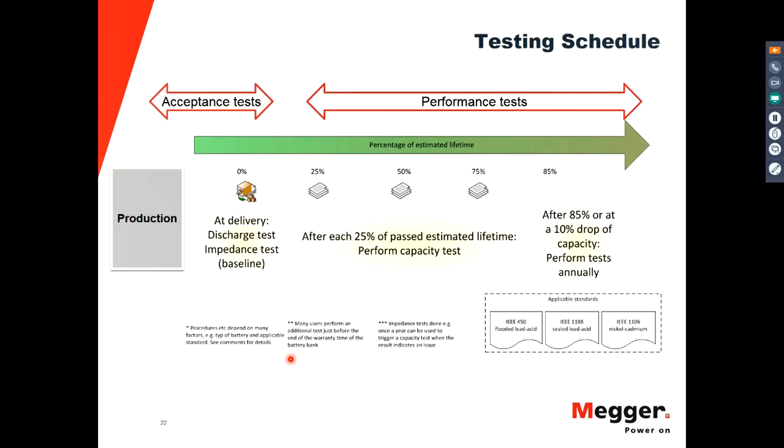So that's a thing that you will hear, that the capacity test is destructive. Well, it's because it's taking life out of the battery. Really, you are just taking 7 cycles throughout the entire life. And batteries are designed for a much bigger amount of cycles. So really, you're not taking too much out of the battery.